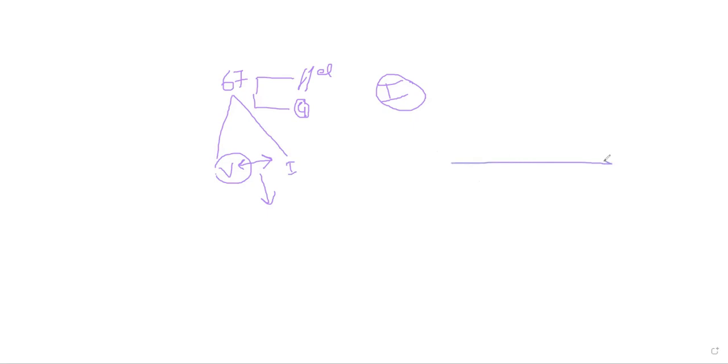Let's assume this is the V reference, the polarizing voltage, meaning the voltage which I am taking as the reference with respect to the current. This is the voltage you are applying to the relay coil. The relay coil again has some inductance. So the flux developed by the voltage is lagging this V reference by some angle of minus phi.